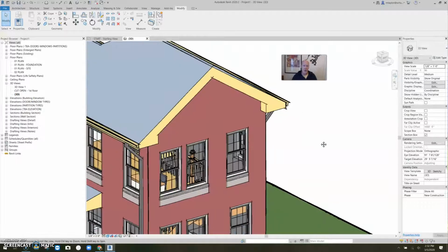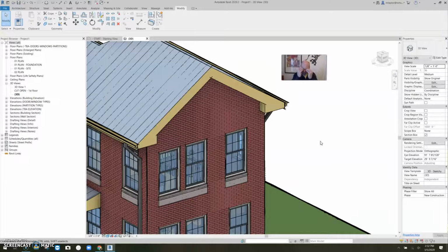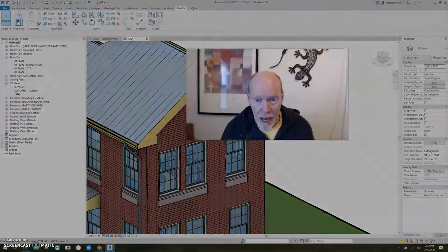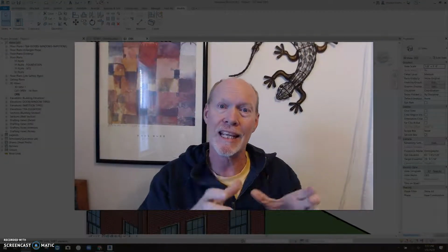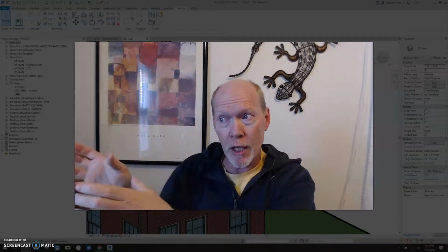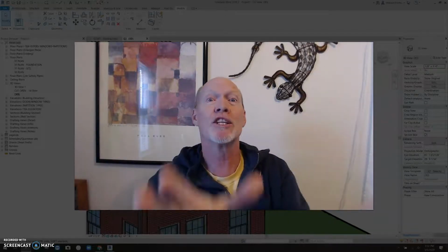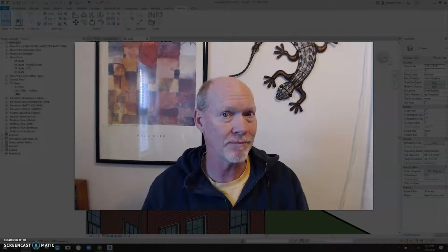Just want to show you how that works. That's a good reason right there for building in place. A model built in place, because I needed the context. I needed the building to be there so that I could build it correctly. For everything else, I encourage you, build models, install them. If you can put it on a truck and drive it to the building site and install it, it should be a family. All right?